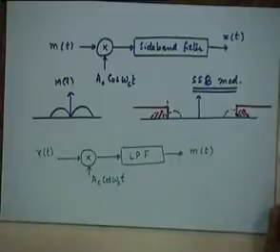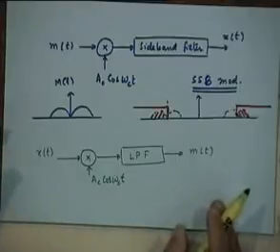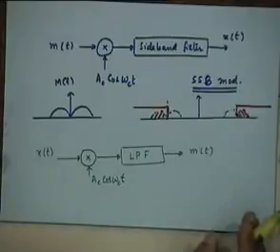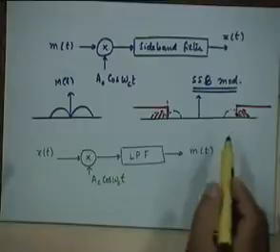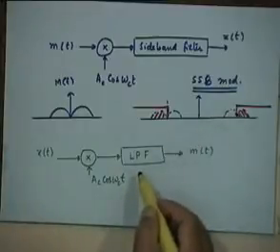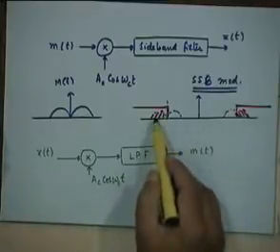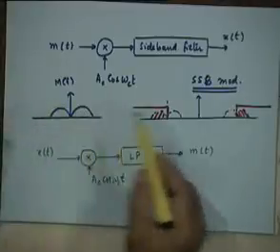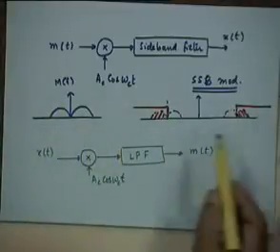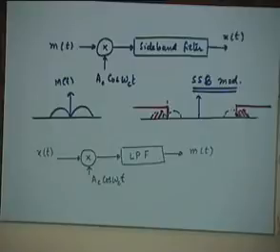So there is absolutely no difference in the demodulation process. It remains the same. Are you all with me? So the demodulator remains exactly the same that we had for DSBSC. Just apply the frequency translation theorem onto this spectrum, and you can see that your baseband spectrum comes back, along with a component around 2f_c, which will of course go.